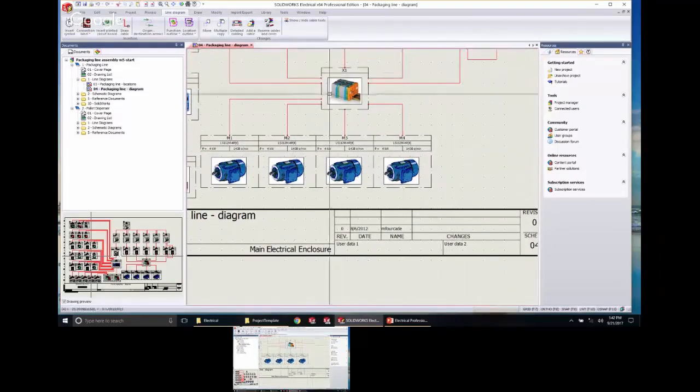To do that, I'm going to insert a symbol. Again, there are different ways to insert components into an assembly. When you insert a symbol, you either have the choice to create a brand new component, and remember, that component is the master, or you can associate that symbol with an existing component. But every component must have a symbol.